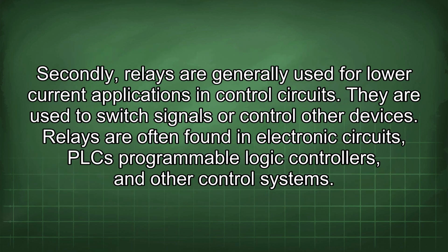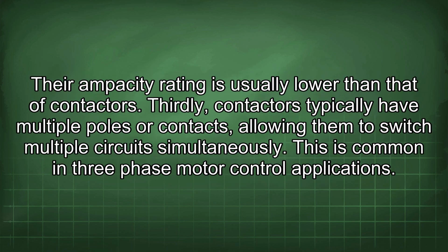Secondly, relays are generally used for low current applications in control circuits. They are used to switch signals or control other devices. Relays are often found in electronic circuits, PLC programmable logic controllers, and other control systems. Their ampacity rating is usually lower than that of contactors.